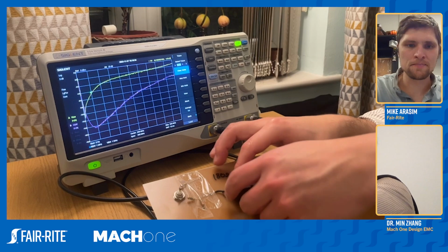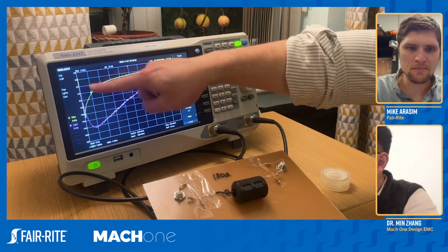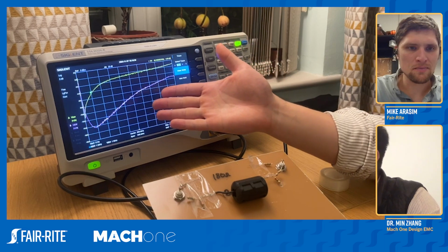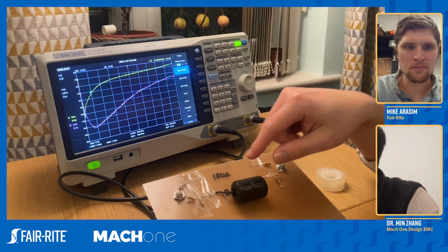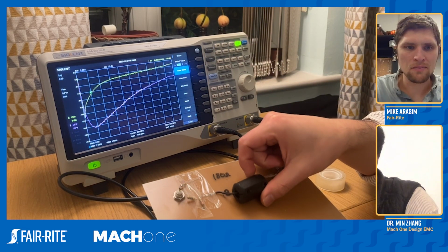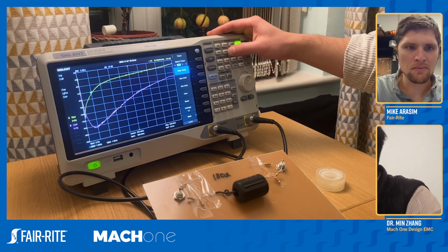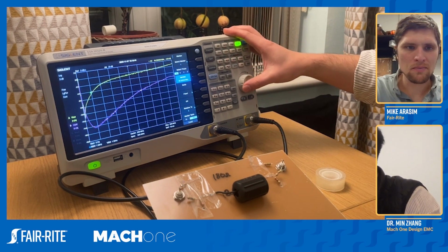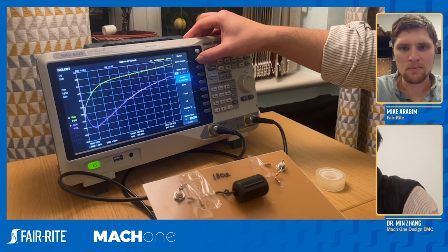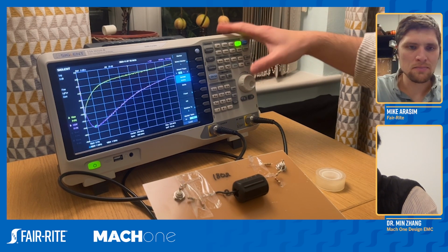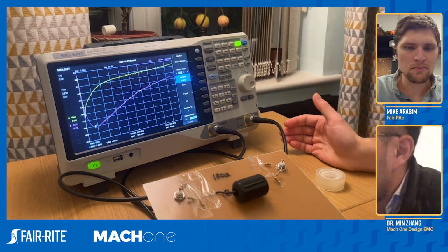And as you can see here, I place a ferrite core on this cable, and I can see the insertion loss, or attenuation, against frequency. This is a 31 material I placed, and using a marker function, I can see that it's most effective at about 40 megahertz.